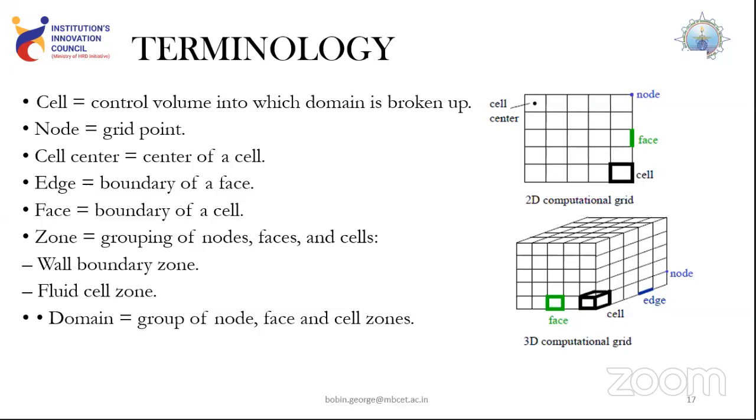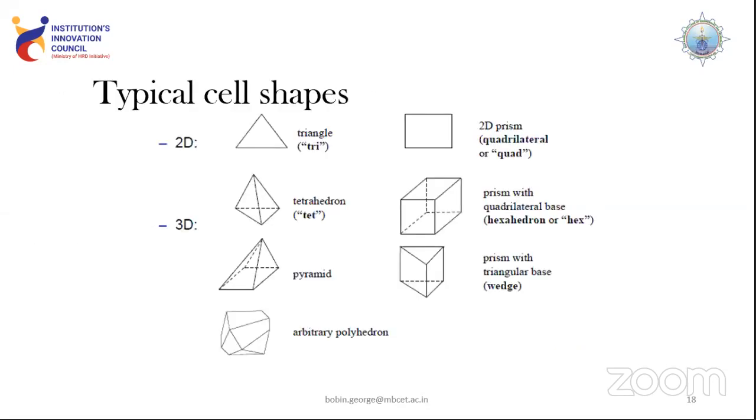first we generate a domain, then we divide the domain into finite spaces, that are grids. Now, coming to the division of grids, whether it is a two-dimensional domain or a three-dimensional domain, you can choose between any of these available shapes. If it is a two-dimensional domain, we can go for a triangular grid or a quadrilateral grid. These are the basic two aspects we have.